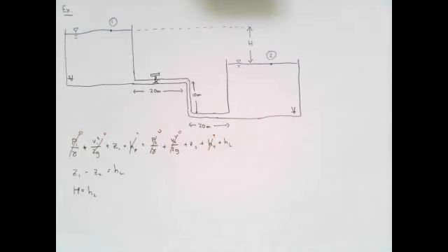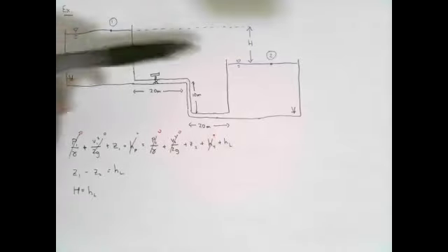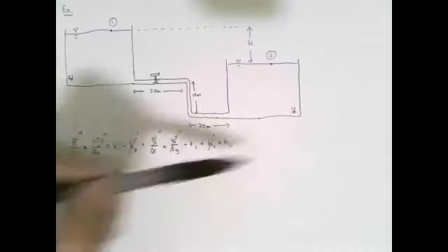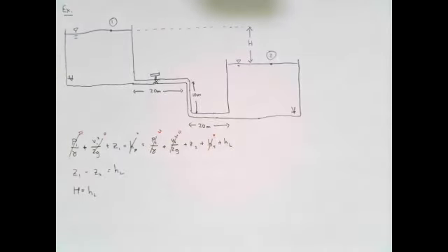essentially corresponds to the loss of energy in the system. And that should make sense, right? From a conservation of energy, that makes perfect sense, right? Because if you have no pressure or kinetic energy, then the loss in energy comes from any energy that is, well, lost, right, as the fluid travels from one reservoir to the other. So that means that all that loss in energy is translated into this system physically as potential energy.